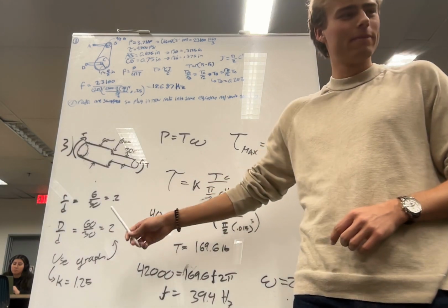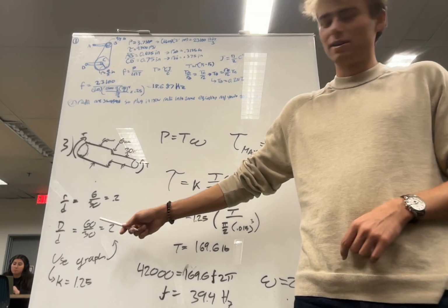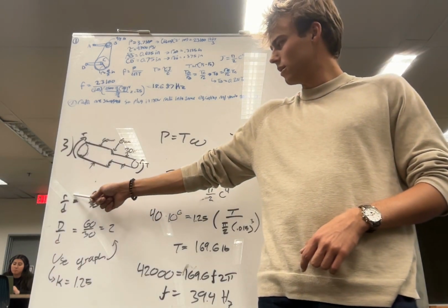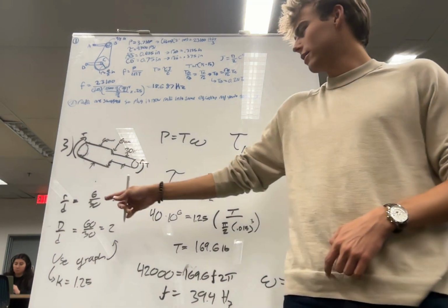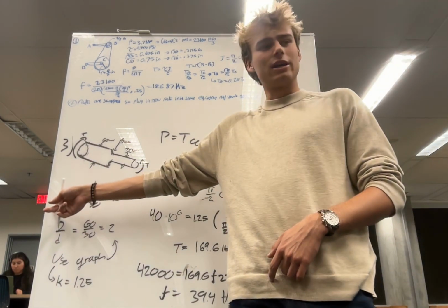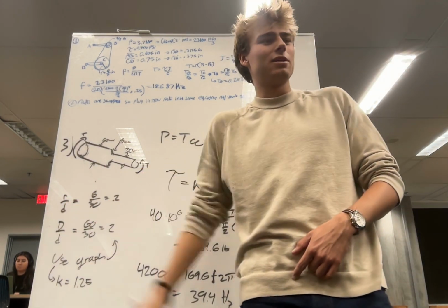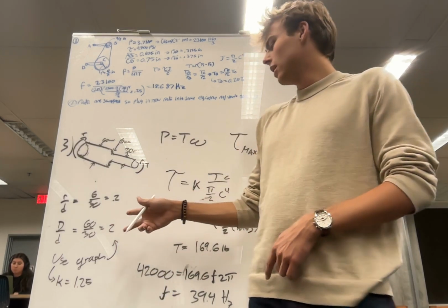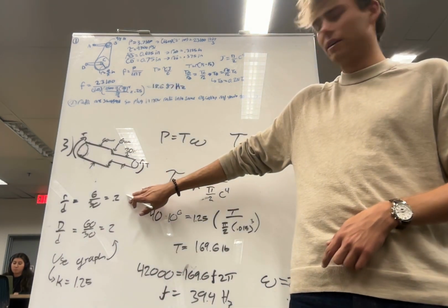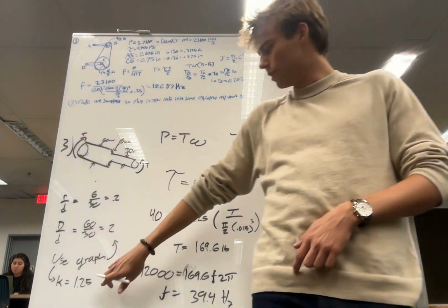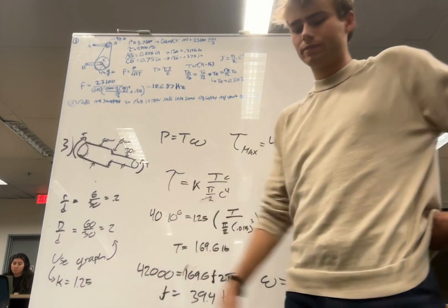That radius is different than the diameter we're using in the denominator. That's the fillet radius. So this is fillet over little diameter, and this is big diameter over little diameter. With these two values, you use this value to find out which curve you're using, and then this will be your x-axis plot, and you should get a value of 1.25 for your factor.